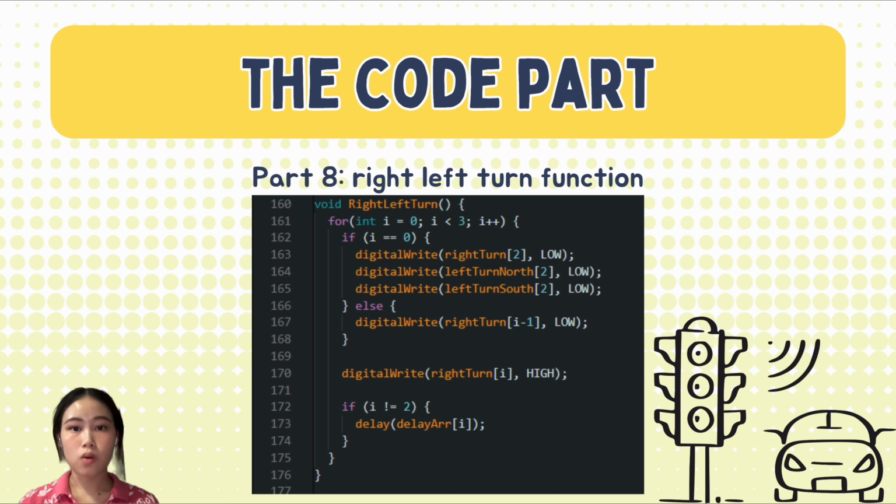Else, meaning the yellow and red lights, set right turn I minus 1 to low. For example, yellow is I equal to 1, meaning the green light is off. Then we set the right turn I to high and use the delay array that we have created.